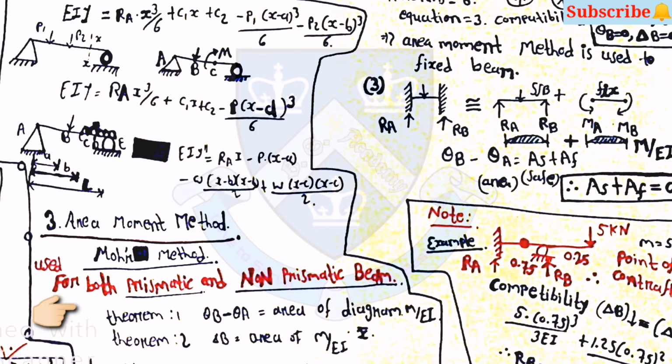Then the third method, the area moment method, or you can say the Mohr method. It is used for both prismatic and non-prismatic bars. In the first theorem, theta B minus theta A is equal to the area of the M diagram upon EI, and in the second theorem, delta B is equal to the area of M upon EI into x bar. So you can find the value of theta B minus theta A by finding the area of M by EI, and for delta B you can find the area of M by EI into x bar.